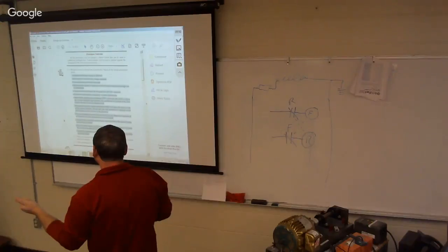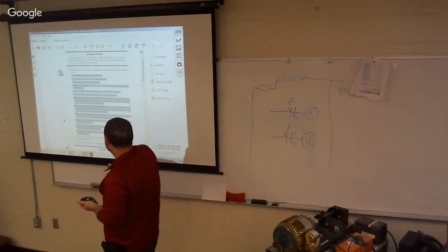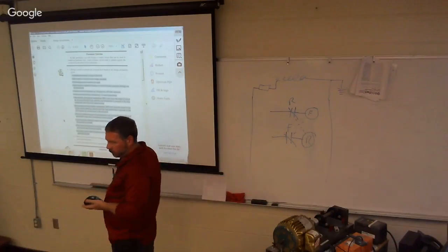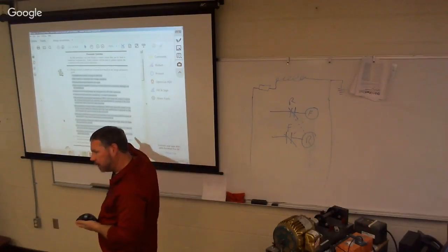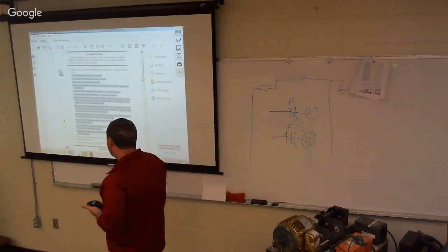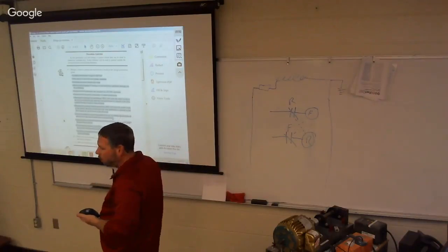Limit switches will be used to sense the over travel of the door in either direction. If over travel occurs in either direction, you will only be able to operate the motor in the opposite direction. That's probably a hint you need to pay attention to when you draw this. And then, of course, auxiliary contact and mechanical interlocking should be used to protect the motor and starter.